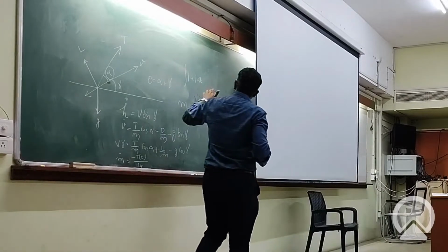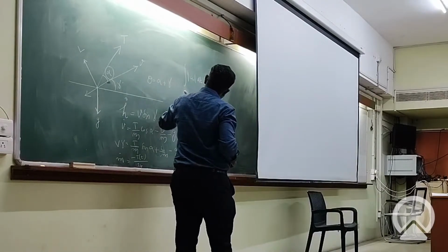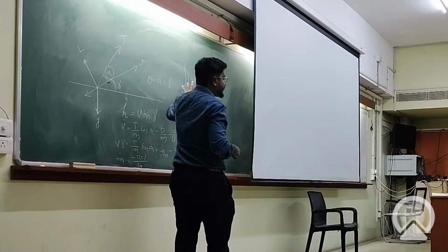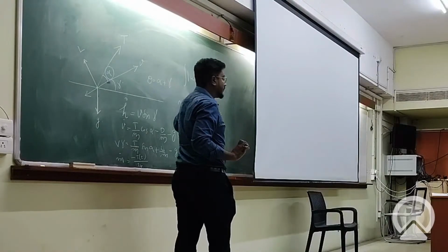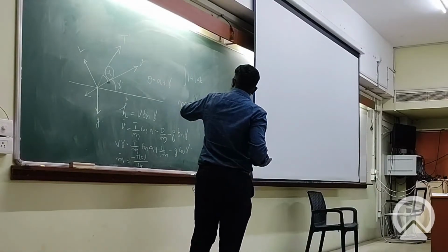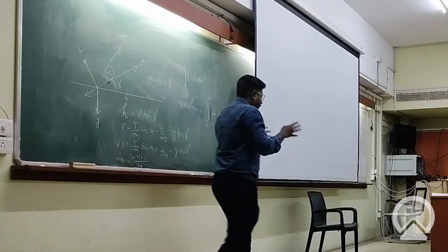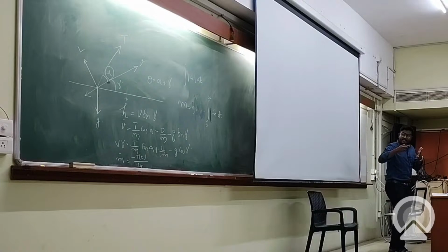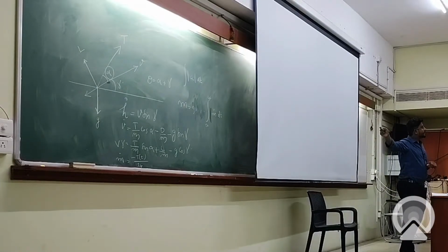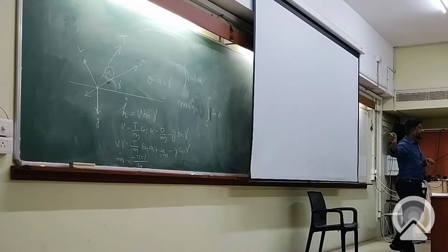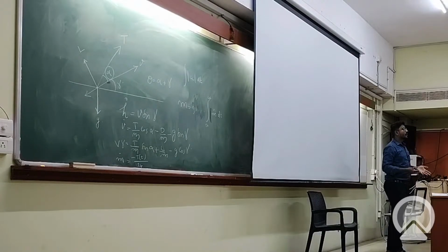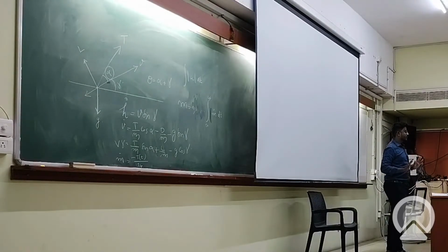Now, when we say that we have to maximize the mass taken to orbit, ultimately it is about the energy expenditure. Now, when you talk about a launch vehicle that carries a satellite to low orbit, the unit is velocity. So a launch vehicle that carries a spacecraft to orbit will contain an integral of acceleration of about 9 kilometers a second.